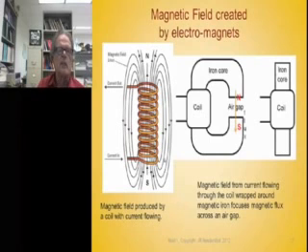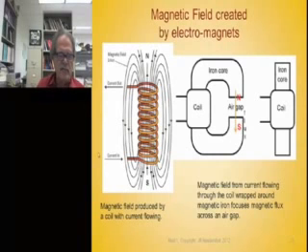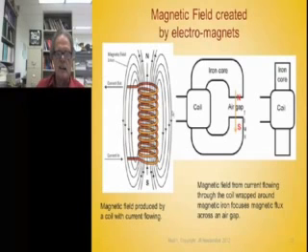So when you collect them all together, you have a toroidal or donut shaped magnetic field that goes around that coil that you see there in this picture, and it's quite concentrated on the inside, but it's not concentrated on the outside, and that's because this magnetism flows through air, and the permeability of air is unity.